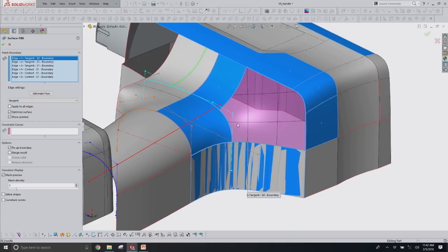When they got rid of the yellow preview, they replaced it with this. So if you see a really square grid, when you have the mesh preview on, you know you're getting that larger surface that's being trimmed back. If you have the mesh preview on and you see a set of meshes that kind of follows this edge, kind of follows what your surface is doing and it looks four-sided, then it's just building a loft. So the whole power of surface fill is when it builds large and trims back. So turn that optimized surface on, I find it doesn't actually optimize anything.